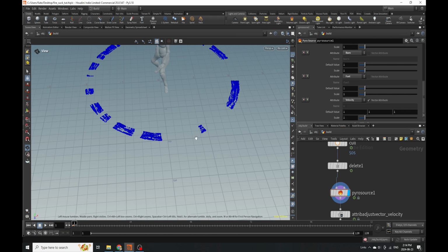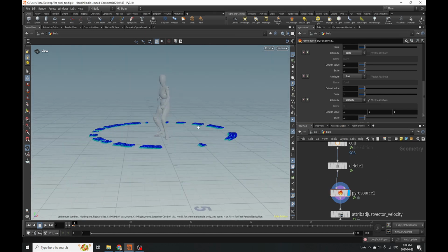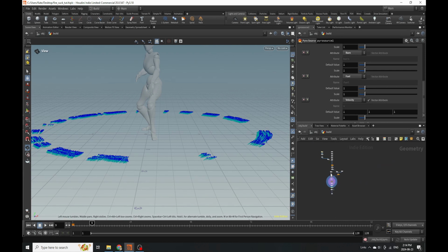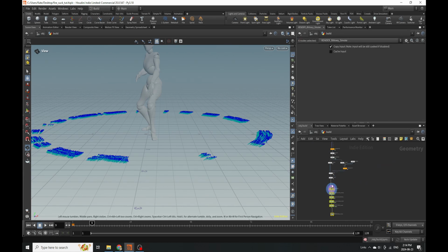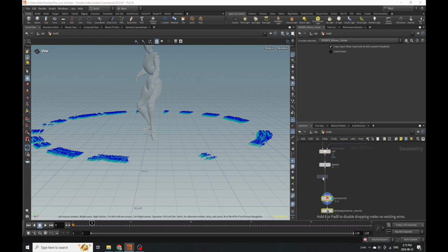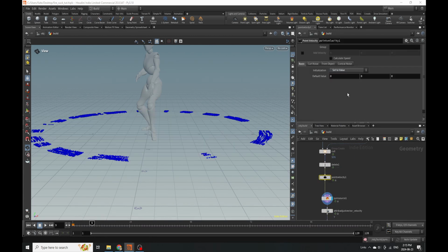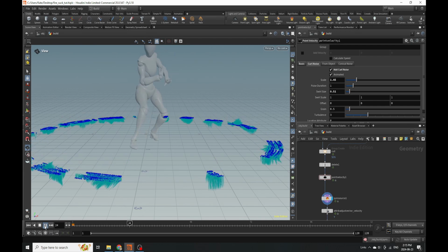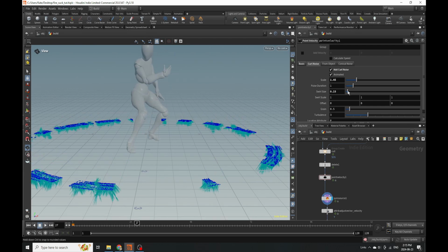Velocity-wise, our points don't really have any velocity. Well, they kind of do. Let's make some better velocity of just the fire going upwards. What we're going to do is go to point velocity stop over here, set the value, and give it a value of 1. Curl noise. And now we should have some randomized kind of movement, which I think is going to be interesting.